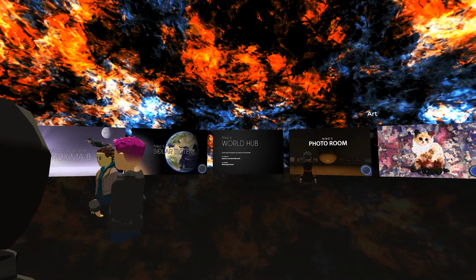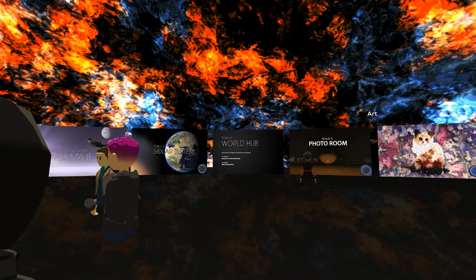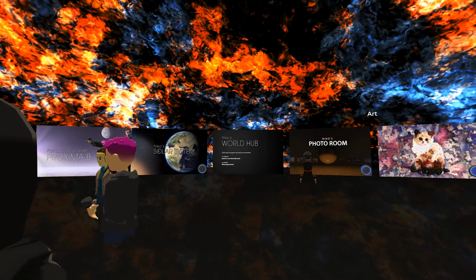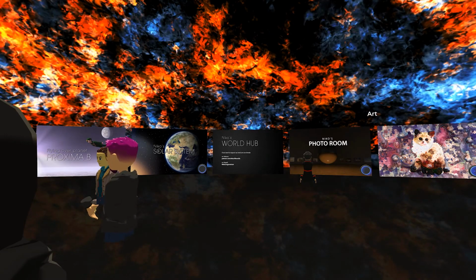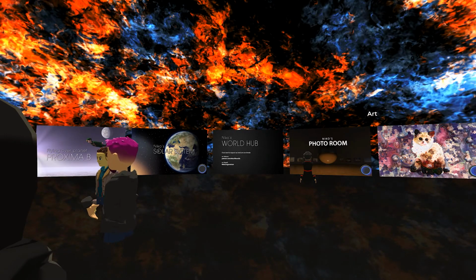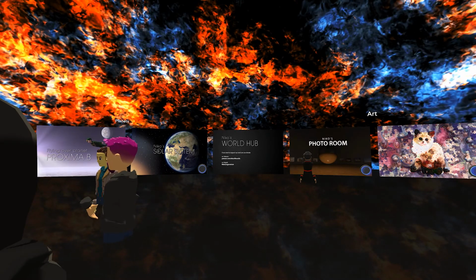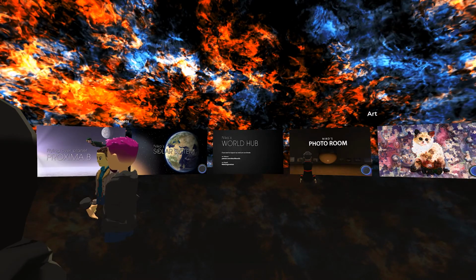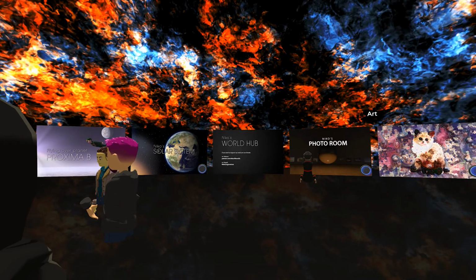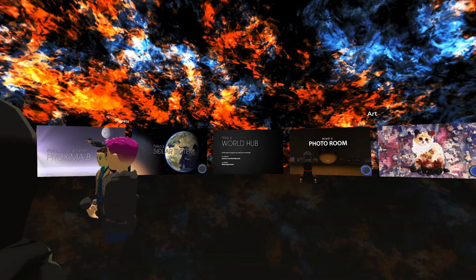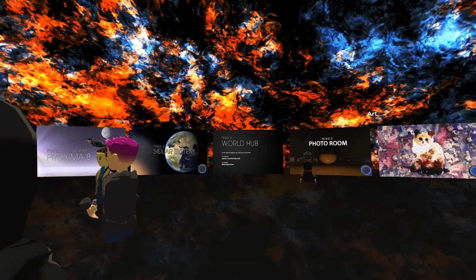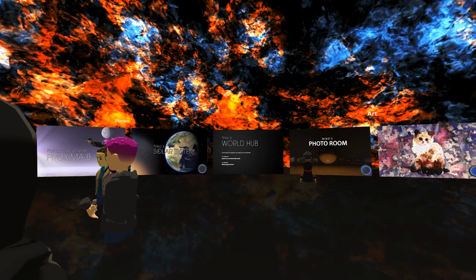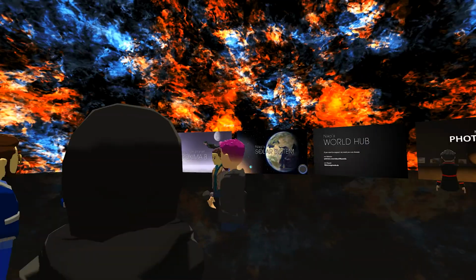I never tried it yet. Doesn't Amplify Shader just make shader code so that you can actually look at the code? Yeah, you can also look at the code. Yeah. So Shader Graph should do the same, and I know that Amplify supports URP, so it should be possible to update to URP and just recompile all shaders. So that's my plan, but I don't know what problems there will be. Maybe some nodes work differently, or maybe some channels are different, or some settings. Those are the details that I still have to find out.